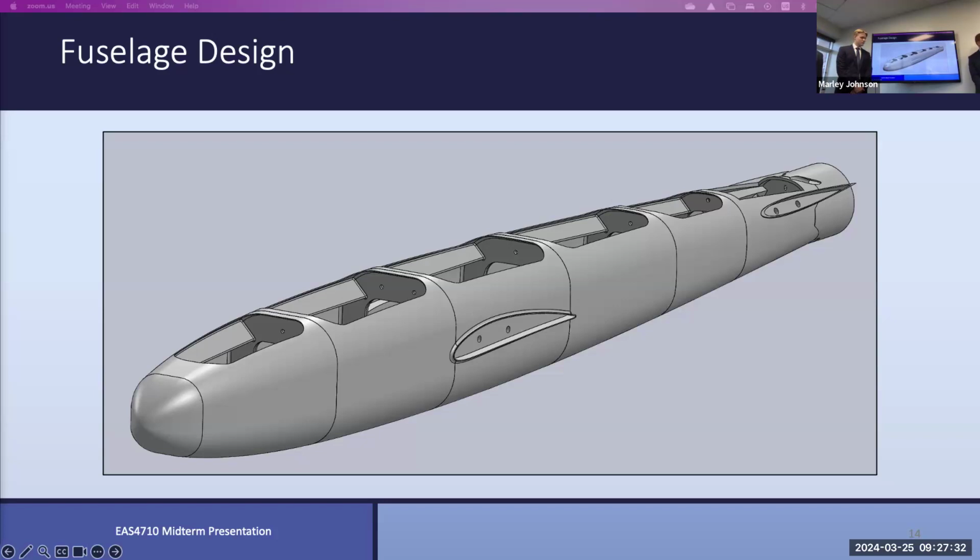I mean, you saw ours with the single layer, we have no issue. And that was also at like 40% density. For reference, the black one there is 32 grams per section. The white one with the single layer skin was 14 grams, and now with the double layer, it's 23 grams. So it's much more optimized than the other one. But that was for the wing, not for the design.